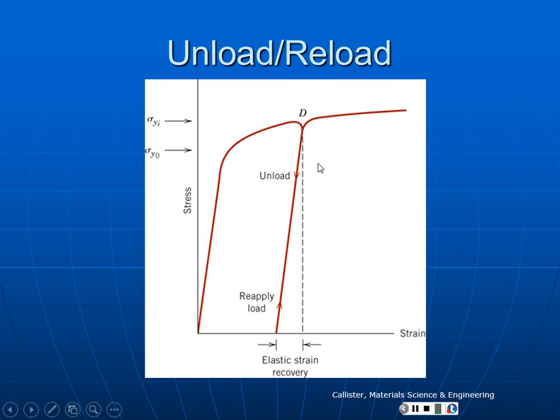And so this could be one big smooth curve, but you could stop many times and unload and resume. Now what you notice, if I were to measure the yield strength initially to the offset, we'd get something about here. Now just pretend I had run this test, unloaded, and gave you the specimen, you wouldn't know it had been yielded already. And so if you ran it, you would see, all right, let's do our offset yield. We're way up here. We get a higher yield point, same specimen.